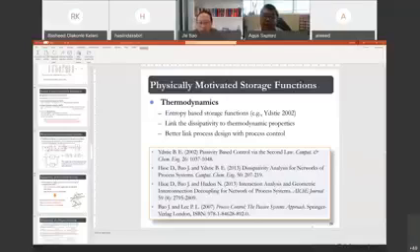If you look at the passivity, no matter what kind of coefficients you have in the PID control, as long as you don't change the sign of the gain Kc, they are always passive.